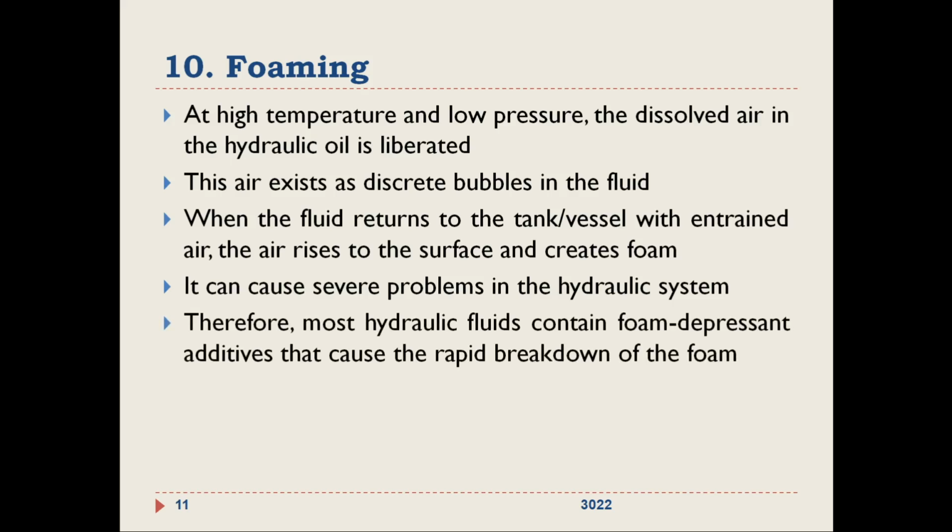Therefore, most hydraulic fluids contain foam depressant additives that cause rapid breakdown of the foam. If there are chances of air bubbles coming to the surface and forming foam because of temperature and pressure variations, additives will be used. It will purely depend on the application. If there are chances of very high temperature and low pressure, appropriate additives to break down the foam or air bubbles will be used.